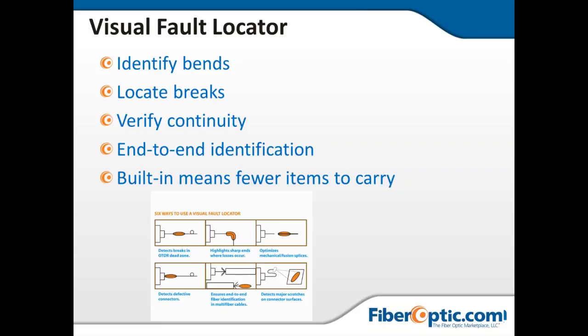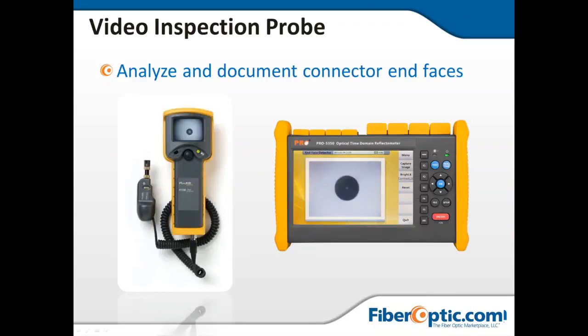Some of the other things that I also identify, it detects scratches, I think, on a connector. So one of the things that I've been able to do is put it on the back of a connector, and don't point it at your eye, but you point it straight up into the air. And if you look at it at a 90-degree angle, like from the side, if there's a little star at the top of your ferrule, there's dirt or debris there. If you wipe that clean, you shouldn't see any kind of star or reflection right at that point.